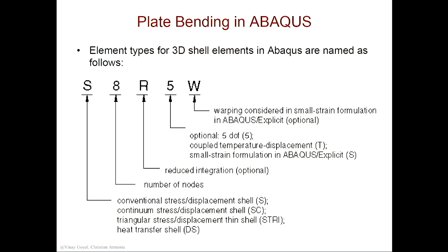I have 5 degrees of freedom: U, V, W, Cx, Cy. I didn't have a Cz, a rotation about z. So now, because I have 0 there, when I invert the stiffness matrix, I could have an issue. So that, for example, Nastran will add a K6 rod to take care of that.